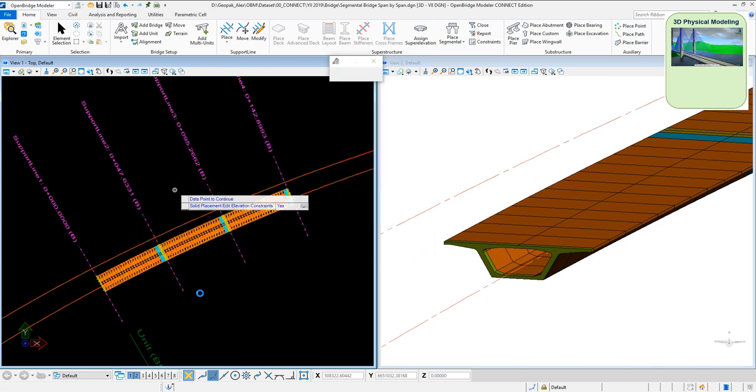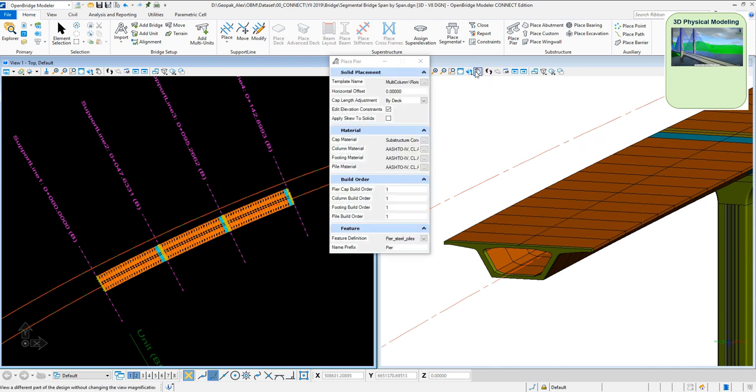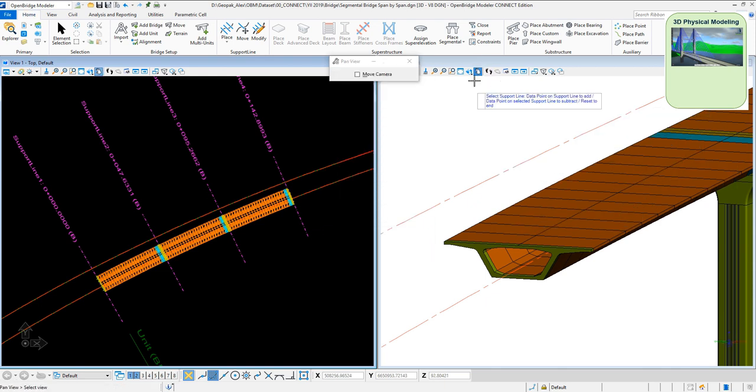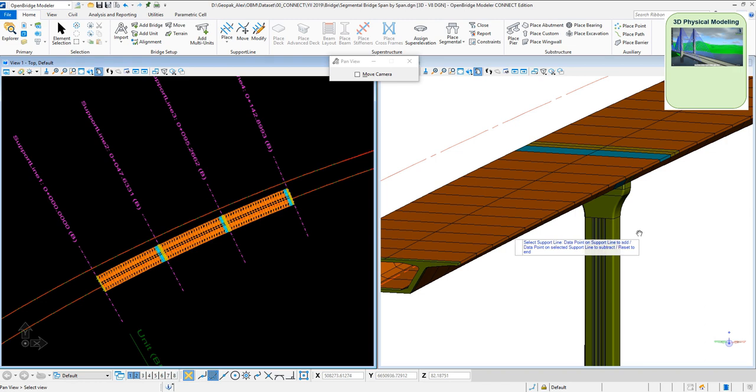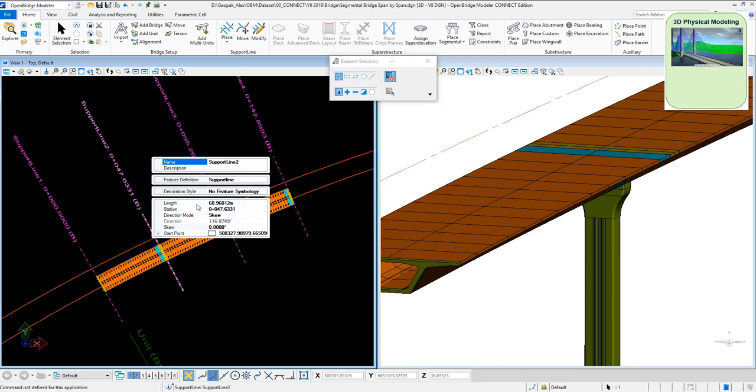Remember, we brought the survey information? Well, we tell them to go 2 meters, 3 meters, 6 feet, whatever units below the ground, and it's reacting to the ground conditions. So the columns, some of them will be taller, some of them will be shorter. Maybe I need to skew one of the piers. So we can adjust the stationing. We can certainly do that without recreating the bridge,